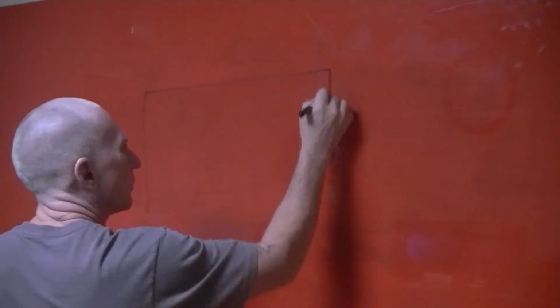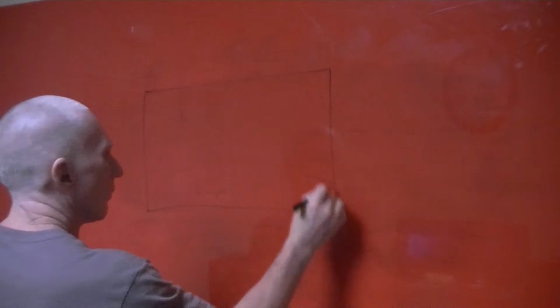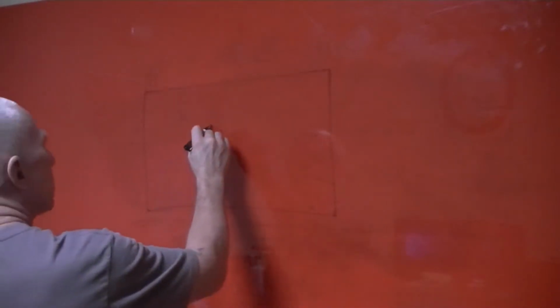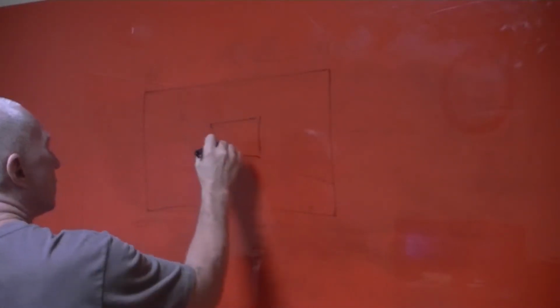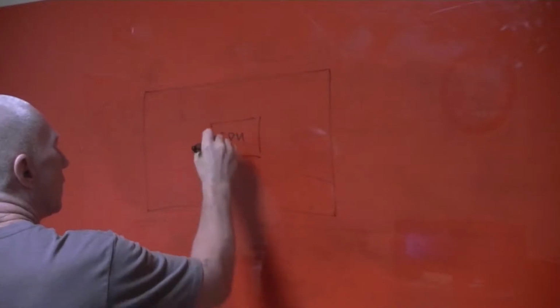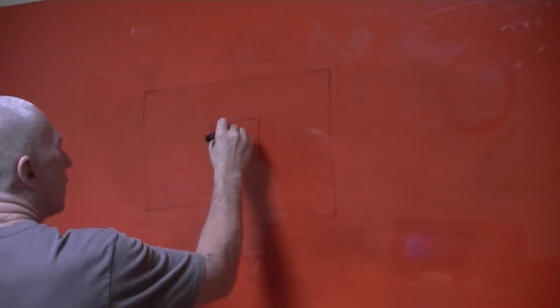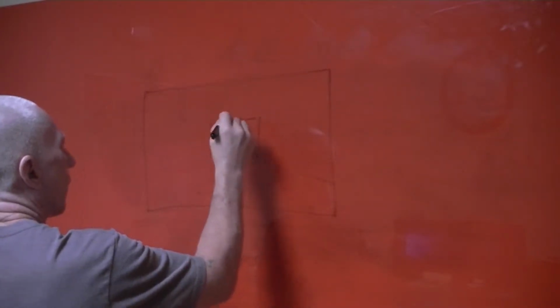Okay, so the next thing I want to talk about is the layout of the circuit board. It consists of about 8 individual small circuits, and so here we have the board. In the center of the board is the CPU. It's a 100-pin quad flat pack surface mount.